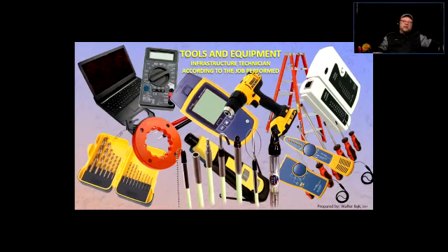And pull that and tie it at both ends, because sometimes when you install EMT, in the contract, it's mentioned that all the conduits and raceways that they're going to install have to be strung. What does it mean that they have to be strung? They have to have strings in them for the next people. If you work for a company that got a contract in installing the EMT raceways, and the contract says they have to be strung, that means probably some other company is going to come over and do the data. Or it could be the electricians do it for you, and you could be the data person. Okay, so you can tie a string and then tie the string at both ends and leave it that way.